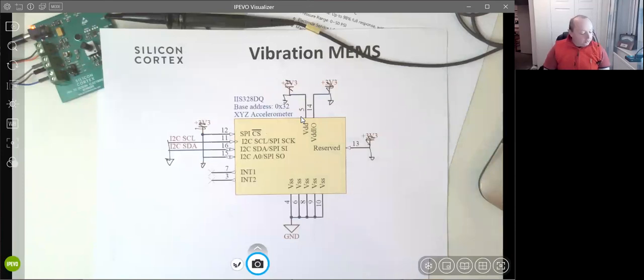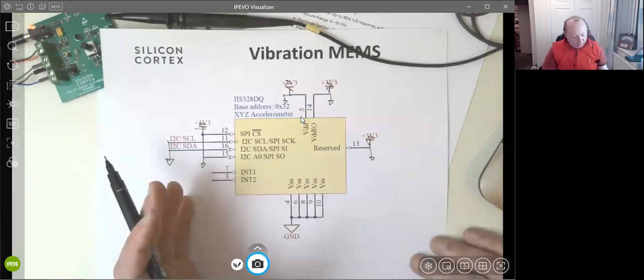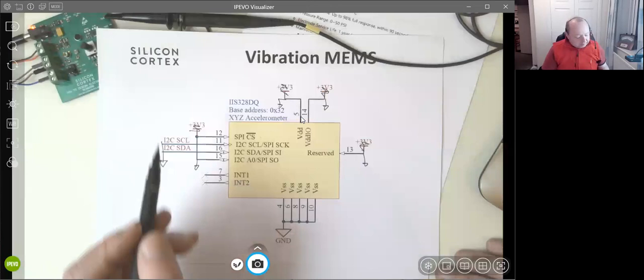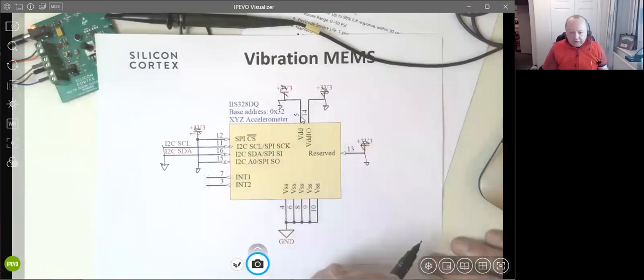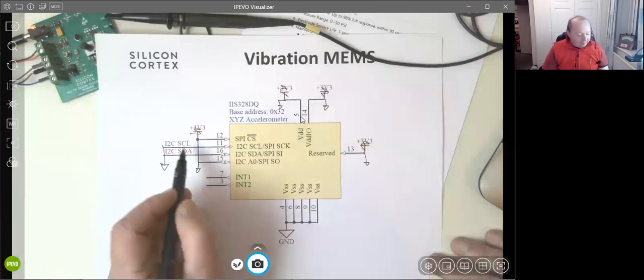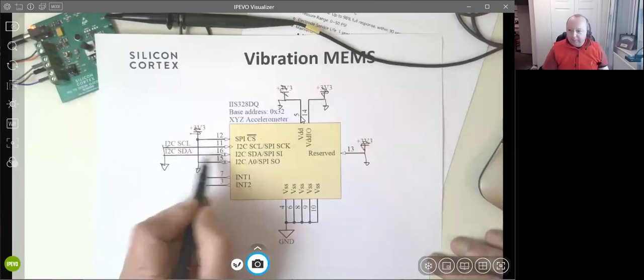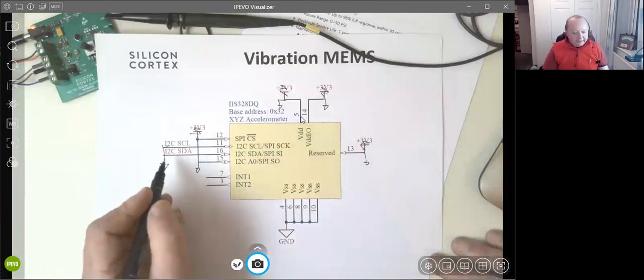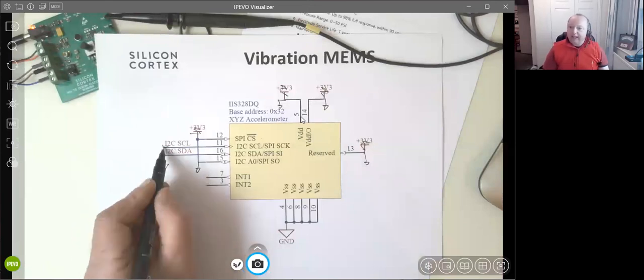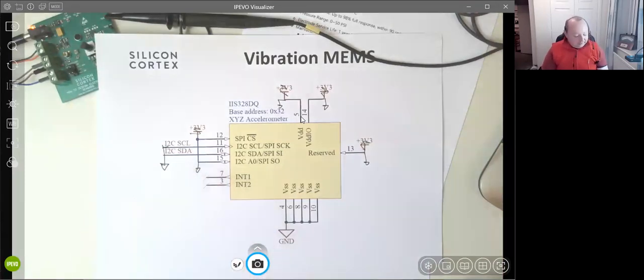And on that note of stiction, when I was coming up with this solution to stiction, which this device does suffer with, I powered the device down, but it still didn't fix the stiction. The reason why was it was back powering through the I2C port and just keeping the device in some erroneous state alive. So I then had to reconfigure the ARM I2C pins to be logic outputs, and then I could drive them to ground in order to solve it. So yeah, a genuine problem.